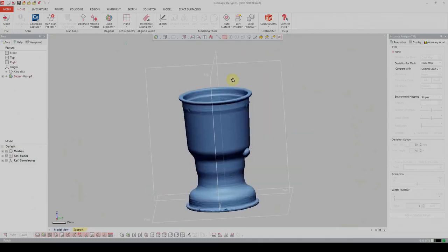These base planes will help me to cut this mesh apart so that I can see inside of this part and extract my reference sketch. But I still need to find an axis which is an intersection of the top and right base planes, because this axis is going to be a reference axis for the revolving part.